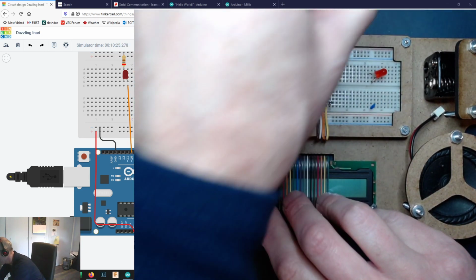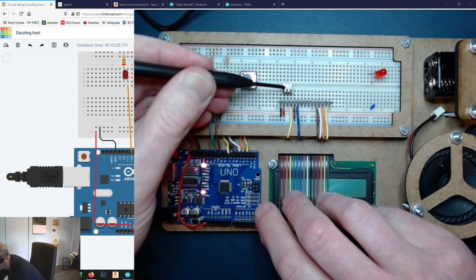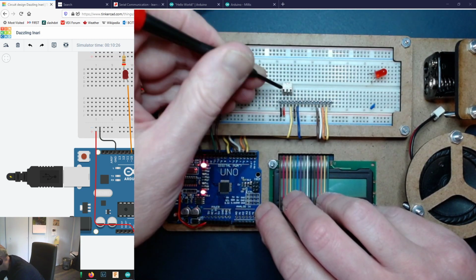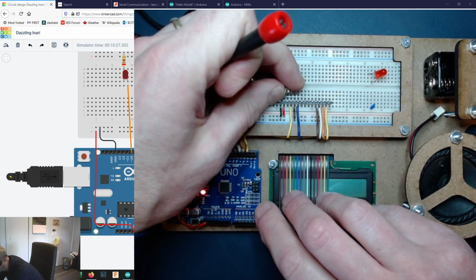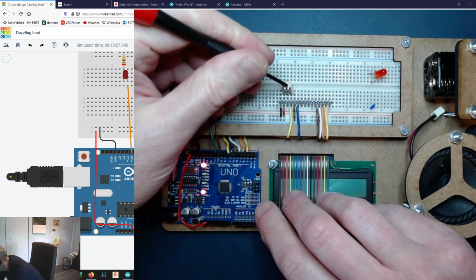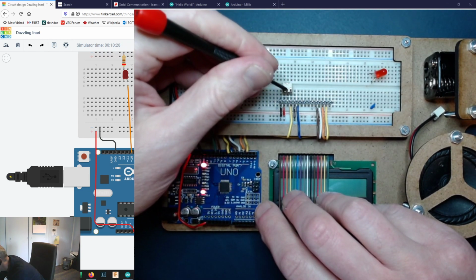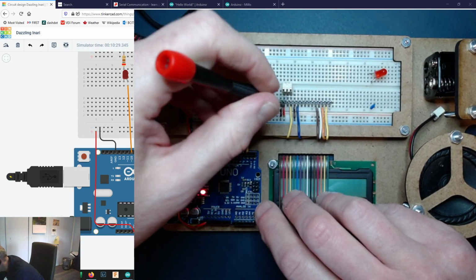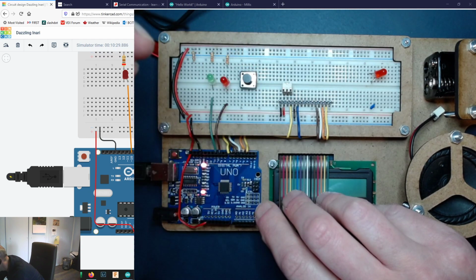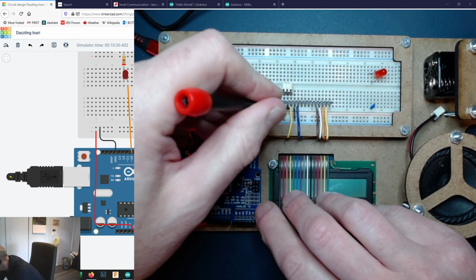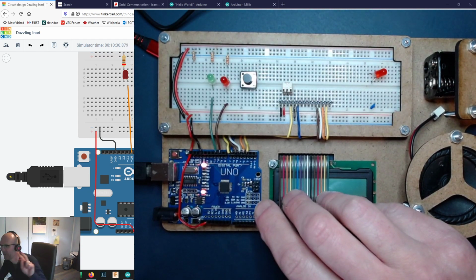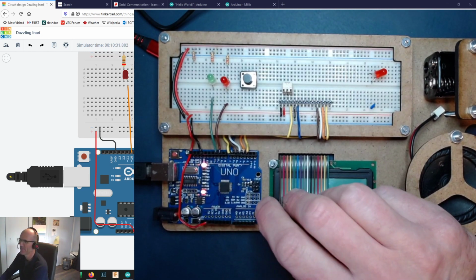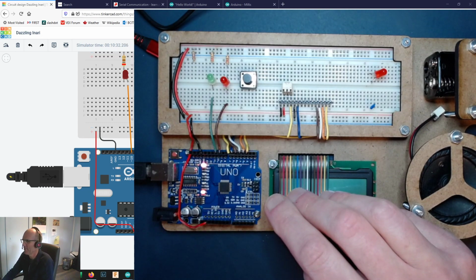And on the Tinkercad screen, because I set the potentiometer up over here, just because of the way Tinkercad was set up, I forgot that by doing it this way, I actually have the middle pin for the contrast coming through right here. And on Tinkercad, that's a green line that we're showing coming into this third pin. And I thought, oh, I've got nothing hooked up there. And so I probably had a loose wire to begin with, and then by fixing it, I moved this over one, and that set me back a little bit and left me confused.